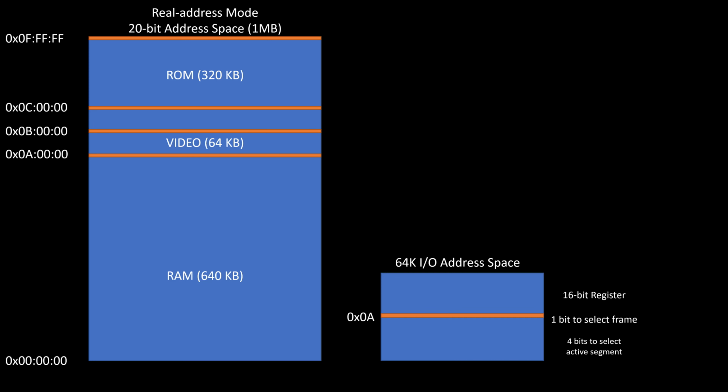If you've been watching my video card series, where I've left that is at A0000, and I'm leveraging 64K of memory for my video, as far as how I get to the memory on the video card. So basically this is just a window through which I get to the full 2 meg on my video card. And then I've had this space between B0000 up to C0000 that I've left open.